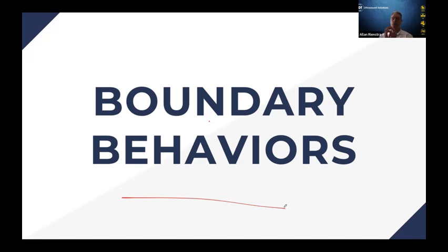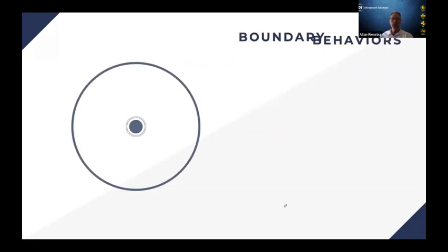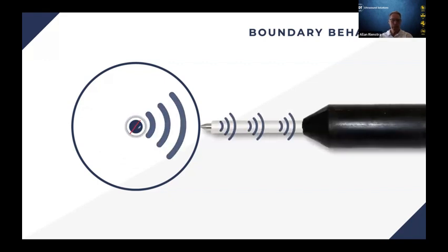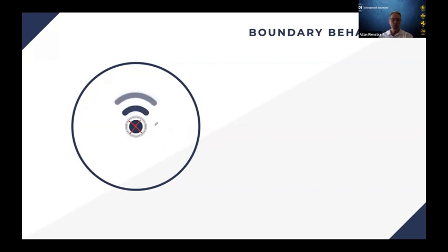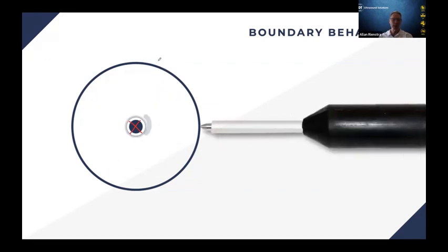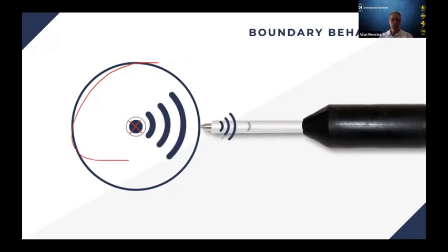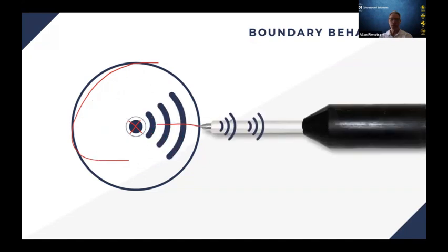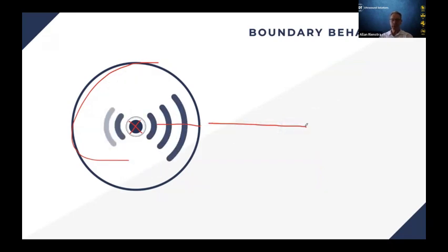So if ultrasound, for example, was produced by the rubbing and friction of a rolling element bearing, that ultrasound wants to stay home inside that bearing. And so we don't really hear it that well with ultrasound. So this is a real advantage for us. And again, with this drawing, the center of the diagram is my source of ultrasound, the ultrasound wants to radiate inside of this volume, but the only way I can get the ultrasound to transmit out of the volume is to use an ultrasonic sensor like this, and then it travels up my sound guide and my waveguide and into my detector.